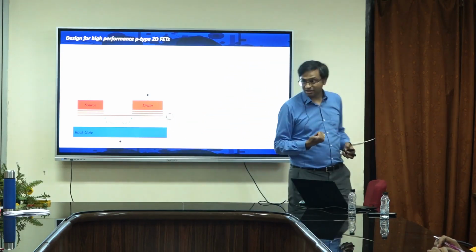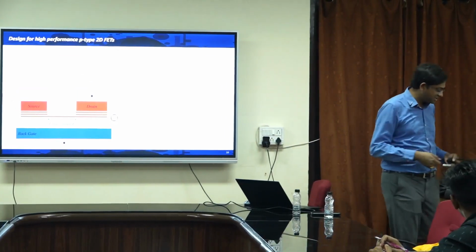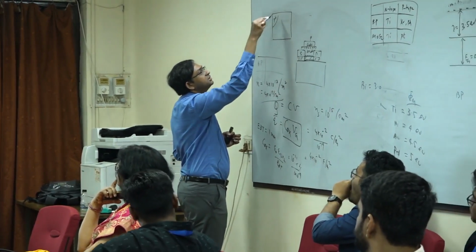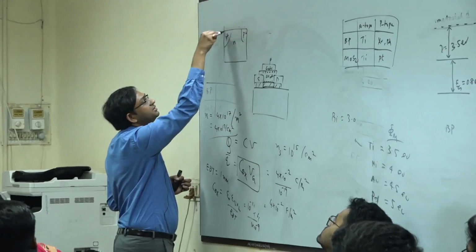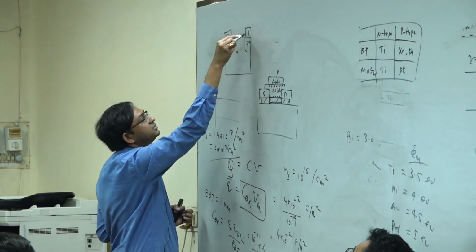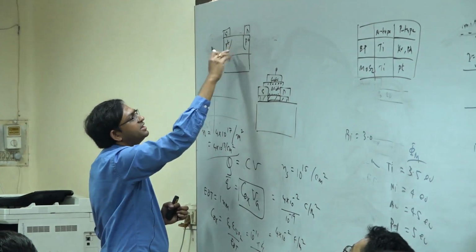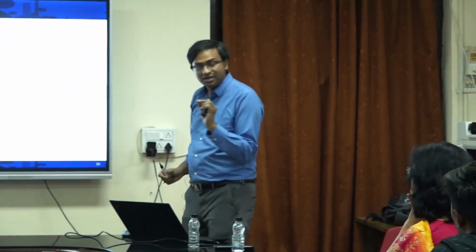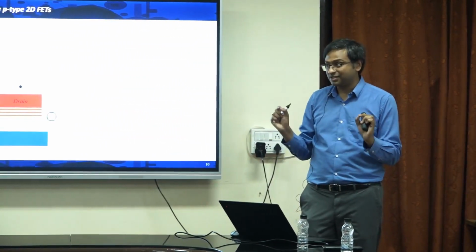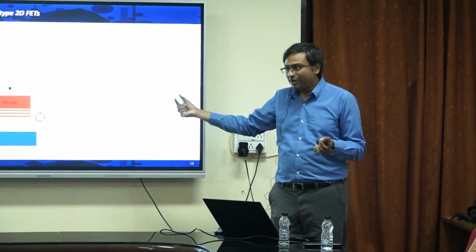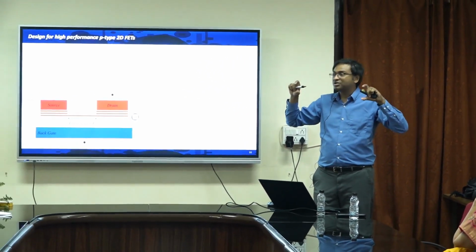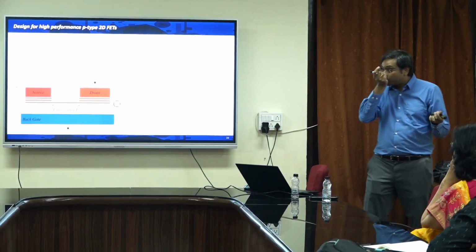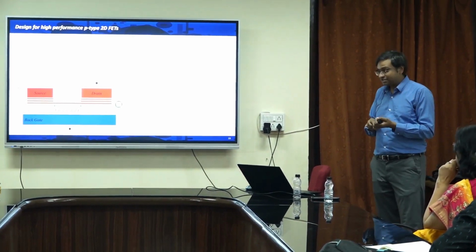This is a device structure that is very similar to your silicon, because remember, in silicon, what structure do we use? There's a P plus, there is N, there is P plus. This is the typical silicon device, source drain heavily doped, and the channel could be intrinsic as well. This is something we could achieve, but now not through substitutional doping, but by designing the geometry, making the contact thick, because thick will remain degenerate, and making the channel thin, because then that will be non-degenerately doped. Correct?